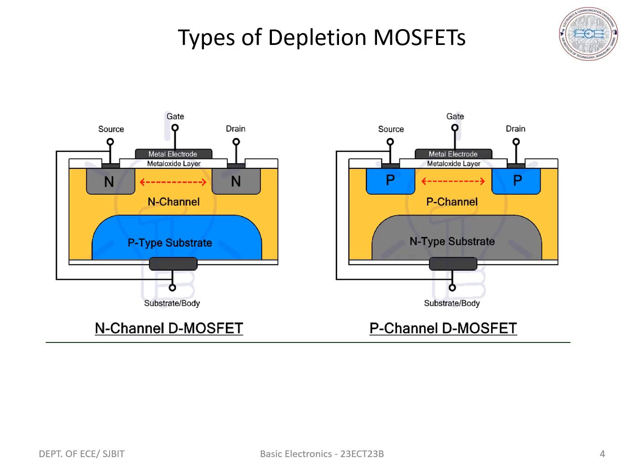All three terminals are connected to metallic contacts. Since we have a metallic contact here, the gate is isolated from the channel. This means there is no direct connection between the gate and the channel in this type of MOSFET. Hence this conducting channel is isolated from the gate terminal.